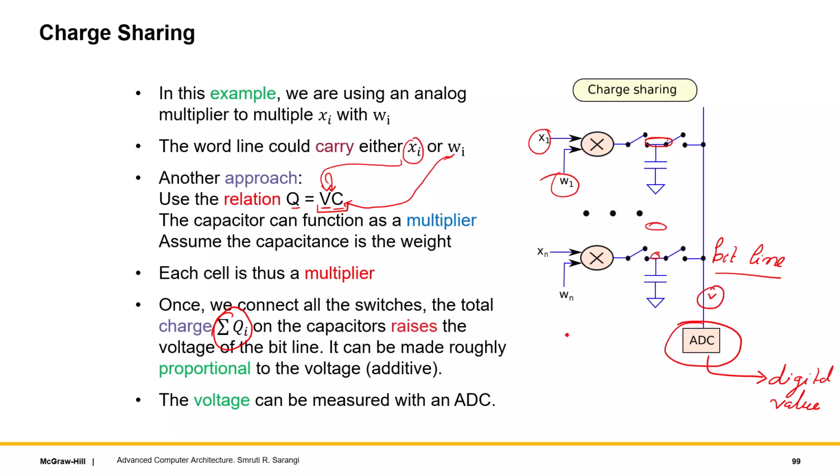So this is an extremely power efficient and performance efficient way of realizing a dot product. Of course, the flip side is that the values of the capacitances have to be changed if you're changing the weights. But if, let's say, the CNN is fixed, this is not a very impractical idea. So this is a neuromorphic circuit because it is realizing a neural network.